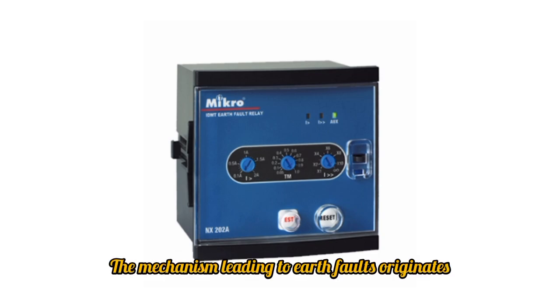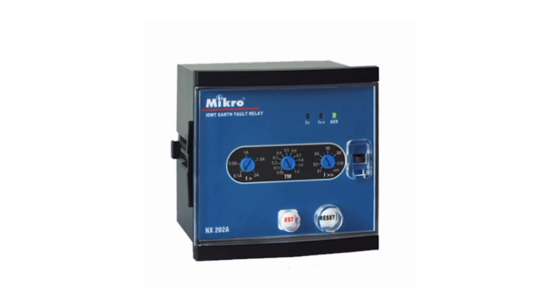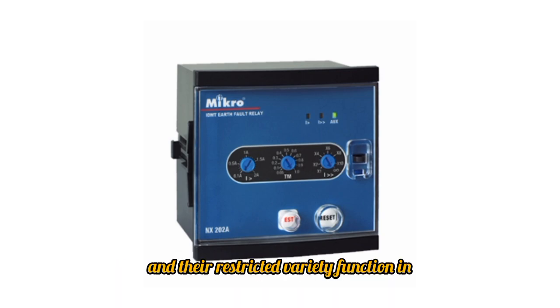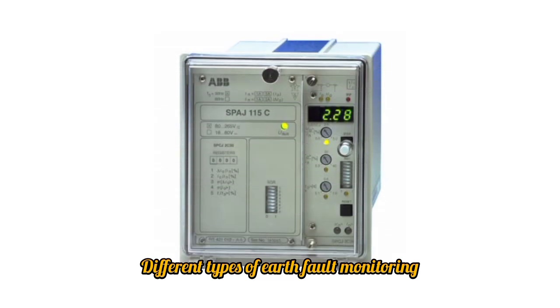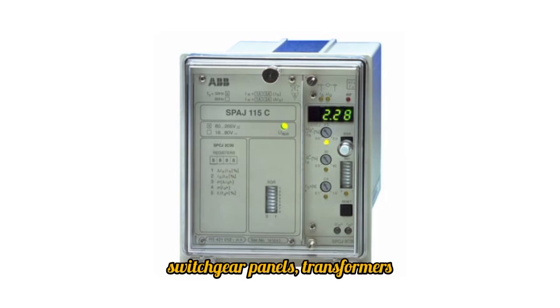The mechanism leading to earth faults originates from insulation breakdown, cable damage, and unintentional conductive part earth points. The main purpose of an earth fault relay is to detect earth leakage currents, which then activate a trip command to separate the affected system segment. Earth fault relays and their restricted variety function in all levels of voltage systems from low to high voltage. Different types of earth fault monitoring relays are installed throughout substations, switchgear panels, transformers, and generators to achieve complete coverage.